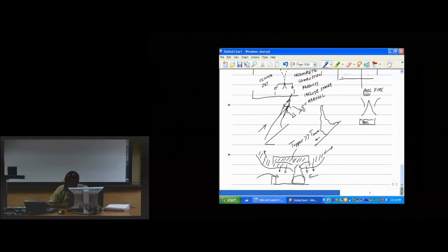One of the concerns with flashover, again, this whole room involvement, is that it can cause a fire to transition from being locally confined to the room of origin to having impact and damage to much larger parts of the overall structure. And it can also penetrate into void spaces within the structure to create a much more difficult firefighting exercise. So this flashover, again, is whole room involvement.